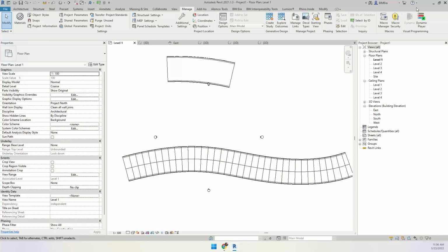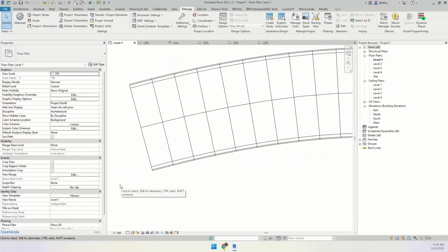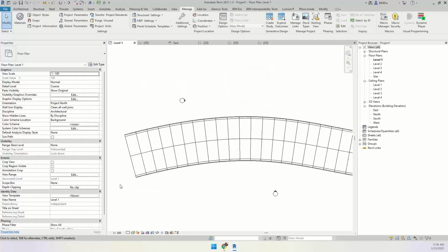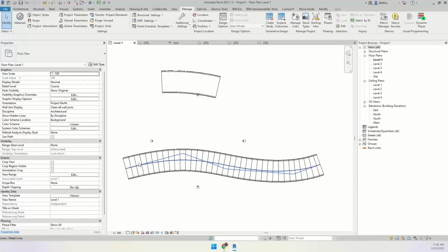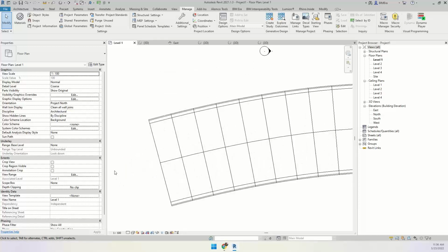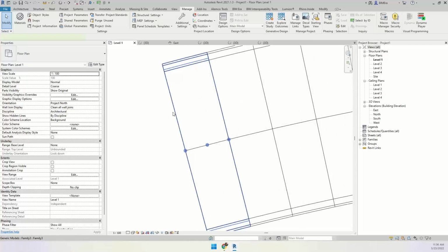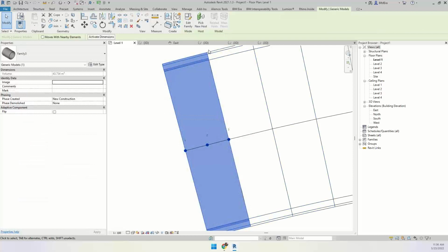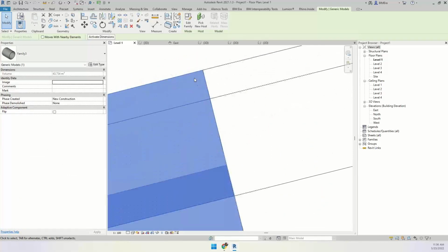Then what would be the biggest difference between playing with 2 points and 3 points? For example, you have this entire curve, and if you want to split that, what will happen? Whenever there is a bend, there would definitely be a sort of difference. But if I use a 3-point adaptive-based family, you don't even see a 1 mm difference.